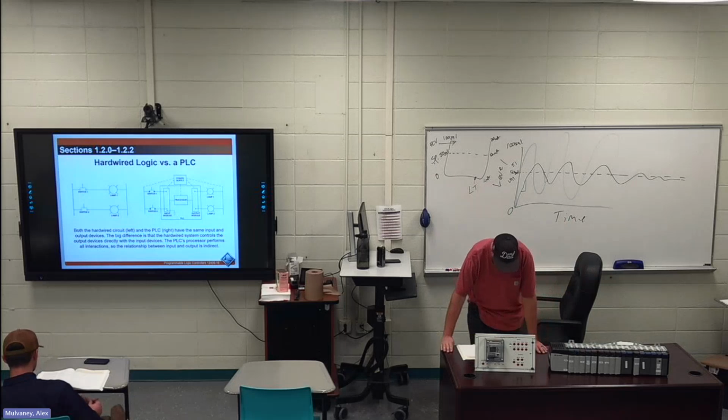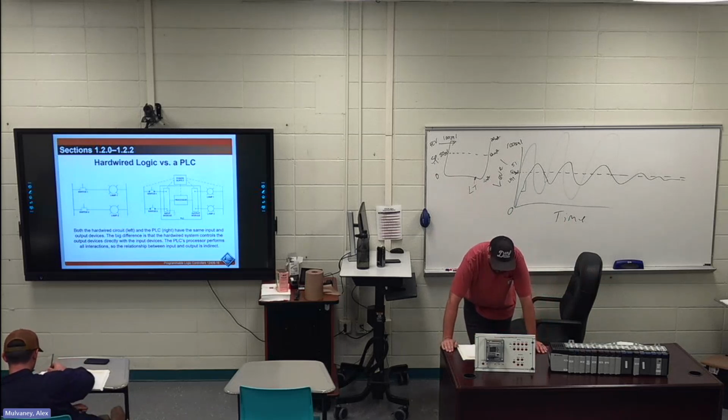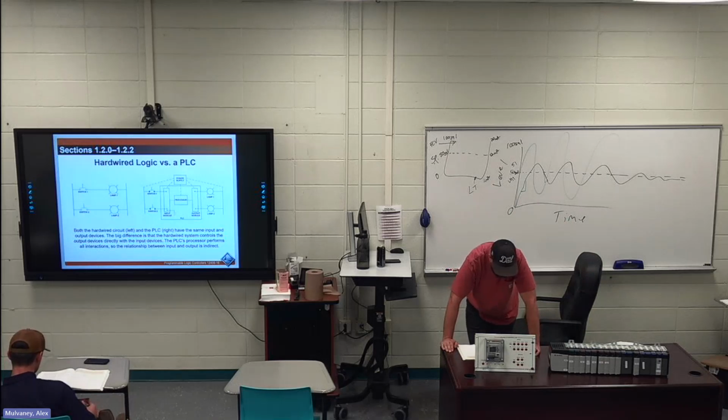The advantage of a PLC becomes evident when circuit changes are required. For example, in order to change the circuit of a hardwired system to have switch 1 control lamp 2 and switch 2 control lamp 1, it would take several minutes to rewire them and would involve moving wires. With a PLC, a simple program edit makes this change without rewiring needed.